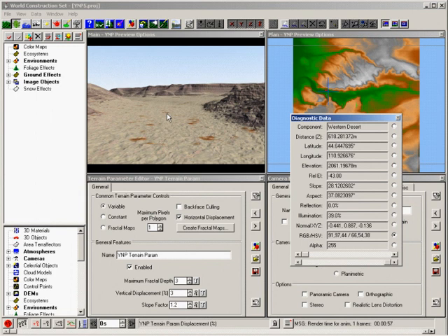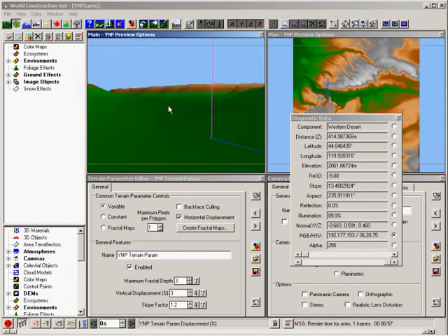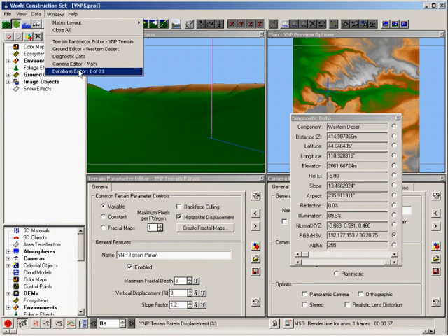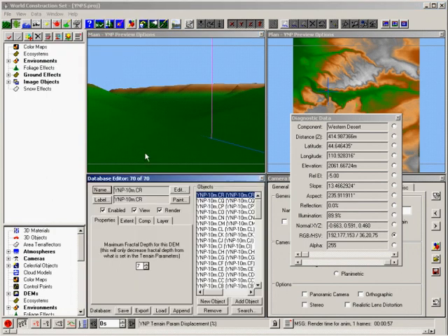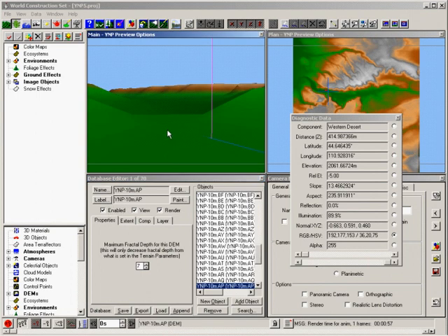Switch back to the real-time view and bring the database editor forward. We're rendering several DEMs that aren't in immediate view, so let's reduce our active DEMs to just the closest ones. Alt-click the foreground DEM and the one behind it.